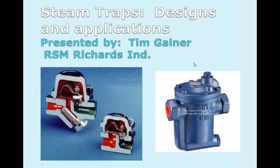Ultrasonic uses sound, and this is very useful if you have a cyclic type, because you put it on the outlet side of the trap, and when it's closed there really shouldn't be a whole lot of ultrasonic noise being generated, and then it opens and you'll get a lot of noise, and then it shuts back off and you should be down to zero.